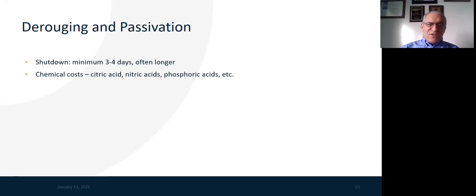There are chemical costs associated with doing derouging and passivation. Primarily, we use citric acid in the United States, but nitric acid and phosphoric acids are very prevalent, especially when there are large amounts of derouging and passivation to be administered.